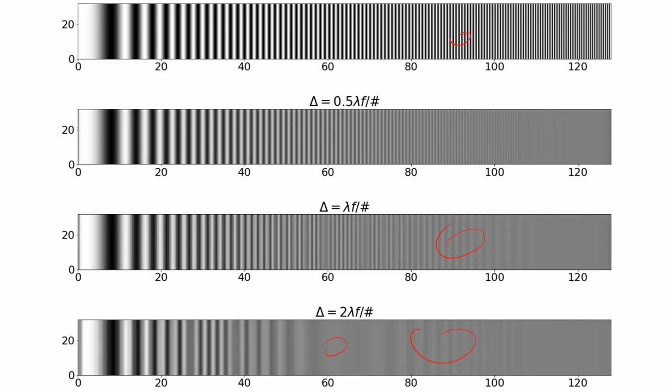It's not necessarily true, however, that you would choose to do this, because the aliasing artifacts are not the only cause of noise in these systems and not the only expense. So here's an example where we've added Poisson noise to these signals, and what you see is that there is more noise at low frequencies in the signal that's sampled at the Nyquist rate than there is in the signal that is undersampled. That's because the undersampled signal at the low spatial frequencies has a higher effective bandpass, as we saw a couple slides ago, and so with this higher transfer function it has less noise at low frequencies.